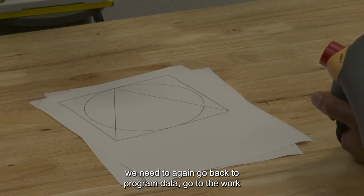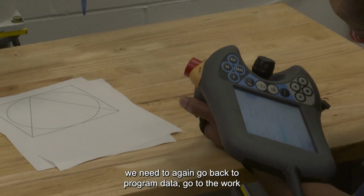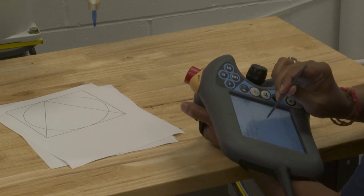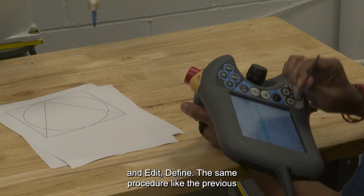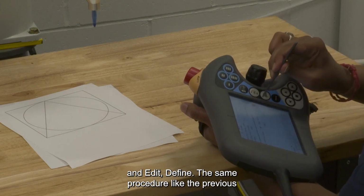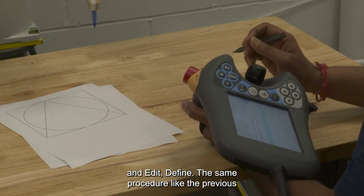So, for that we need to again go back to program data, go to the work object data, just like how we did previously, and edit, define. The same procedure like the previous time.